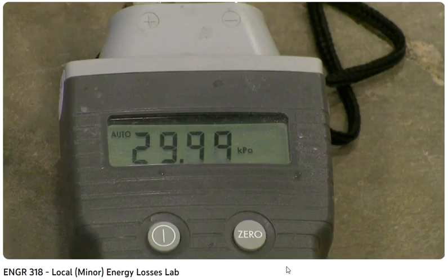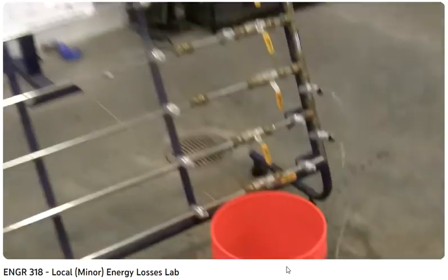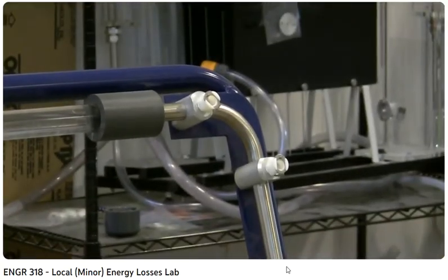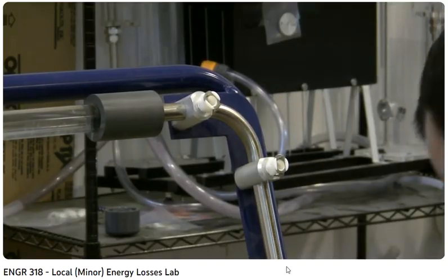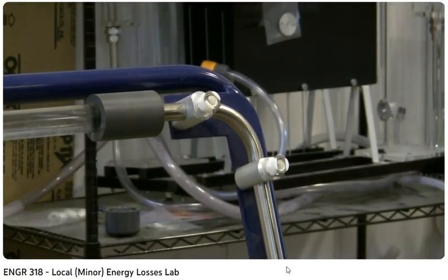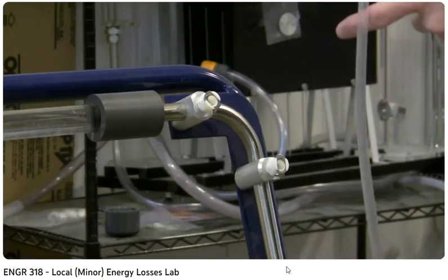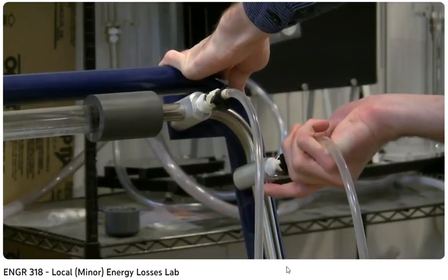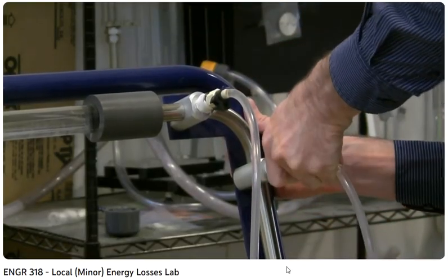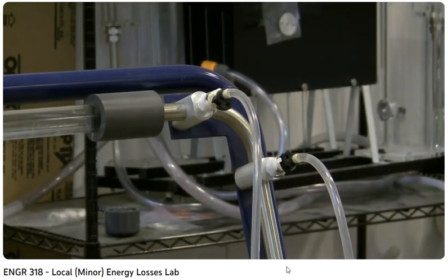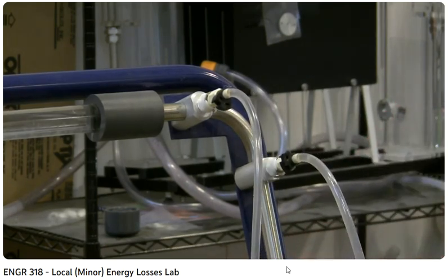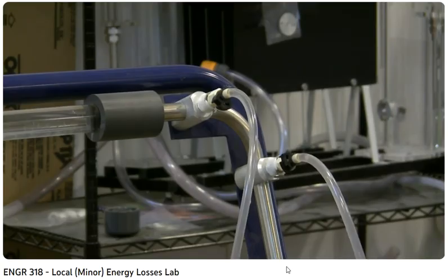Okay. Next, the short radius 90-degree bend. All right, I will plug in the taps to it. Now, each of these fittings that we're doing thus far are going to be energy losses, and so really the pressure is decreasing. I haven't been real meticulous in noting which tap is the upstream tap and which is the downstream tap, simply because I know that all of these are going to induce an energy loss. And again, I've got an air bubble that I need to get rid of.